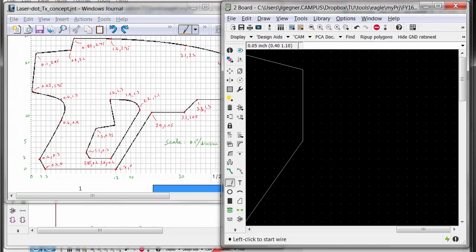And all these coordinates are pretty much in increments of 0.05. So if you do that, then you can actually just click without entering coordinates and you'll be spot on. But don't do that unless your grid size is actually the same increment as the smallest increment that you have in the coordinates that you are entering. So I'm going to get the bend here, and I'm going to click here. Oops. You can also right click, it'll go through it.